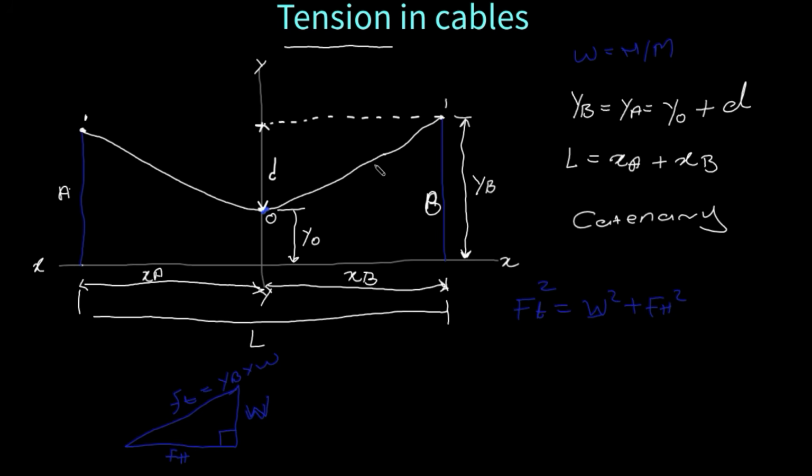If we are here, let's call this point Z, then we are doing calculations about this point. We want to find the tensions on this point. We are going to take the length of the cable from the turning point to that Z point, and this weight will be from the turning point O to our point Z, whereas w will be the Newton per meter.